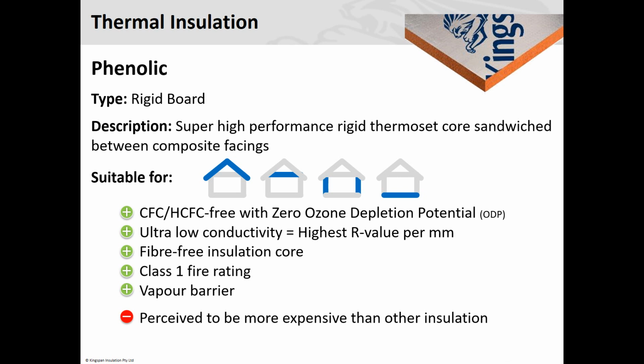Sorry to digress a little bit, but for the hanger system for that Cool-Therm, do you have a hanging system that sits over the joists, or do you screw it? Are we talking about what application? For your suspended floor. Okay, for the suspended floor, there's a couple of things you could do. If you had a suspended timber joist floor, let's say these were your joists, say every 450, and you wanted to put the Cool-Therm in there, you'd have to build a batten type system, and then put your rigid board on top of the batten, so you'd have your insulation in here.